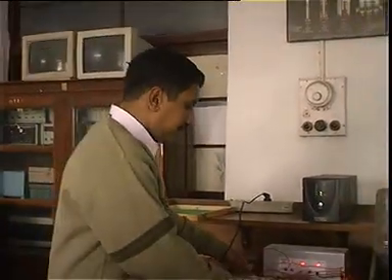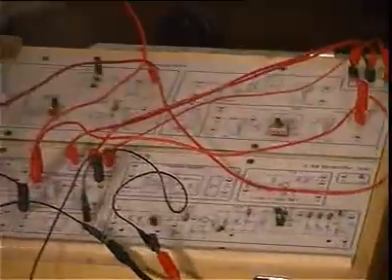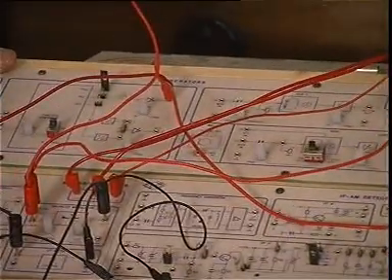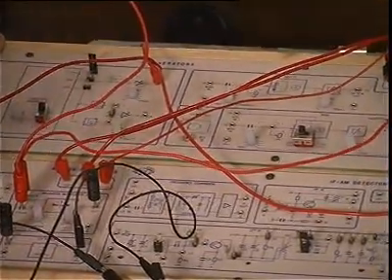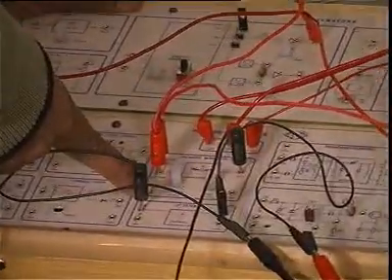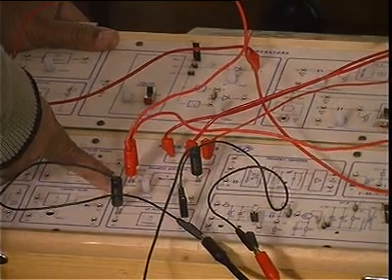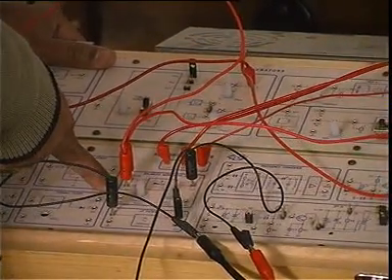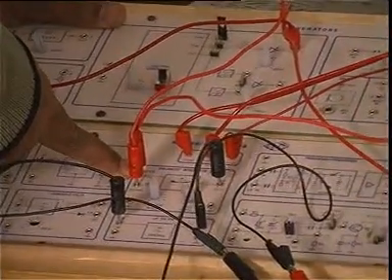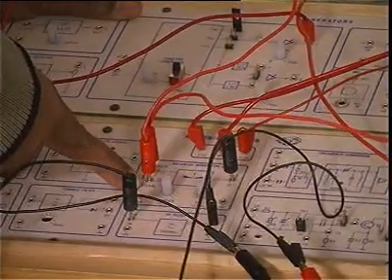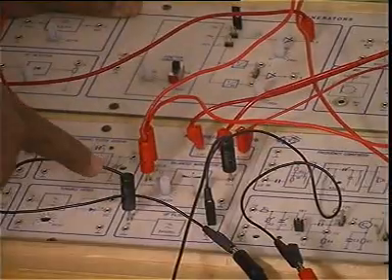Now in this kit, I showed you when we talked about modulation that this was the carrier frequency circuit, the circuit that generates the carrier signal. When I am doing a synchronous demodulation, this is another balance modulator. To one input of this modulator, I'll give the modulated signal, and to the other input, I'll give the carrier signal. This is a locally generated carrier signal, and this is the modulated signal. The demodulated signal will be available on low pass filtering.